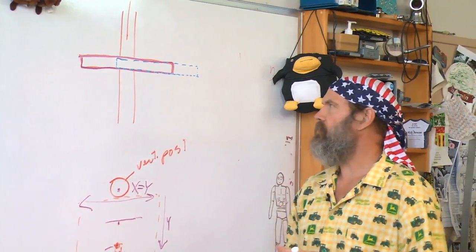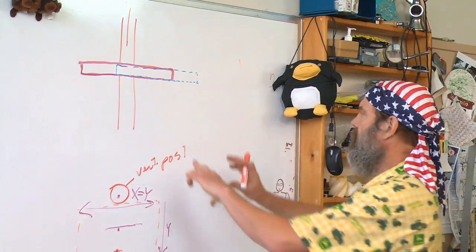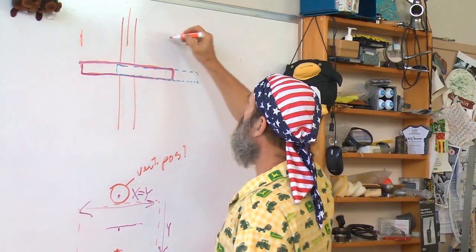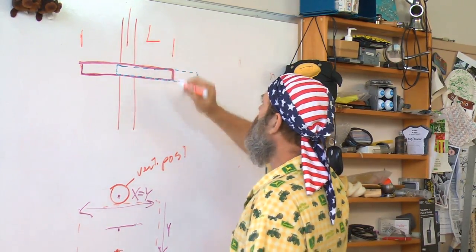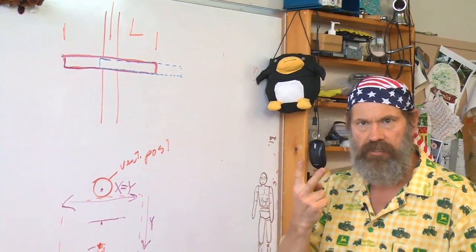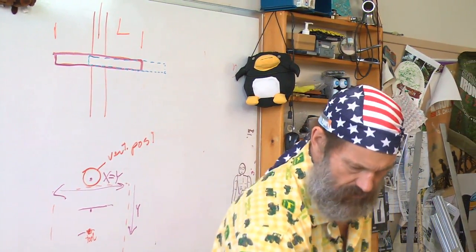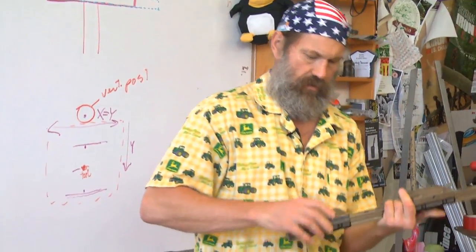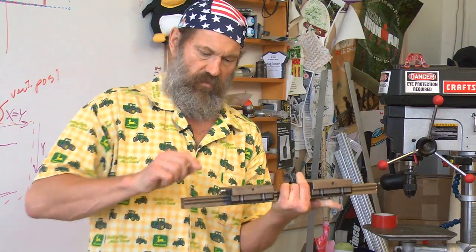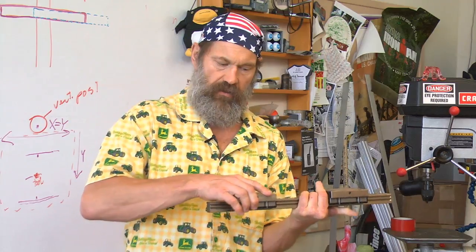Remember Saint-Venant's principle. What does Saint-Venant's principle tell us? Well, I need to have certain proportions. And if this table is L length, I know if I'm going to do linear motion, I'm going to have some bearing support. And I have two options. I can, one, fix, for example, the bearings on the table and have the rail fixed to the base so the table moves on the rail.